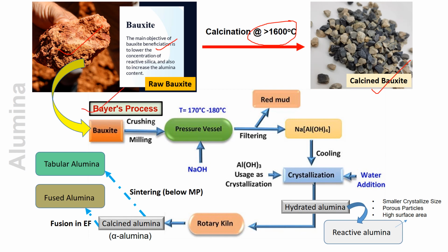Bayer's process converts bauxite to pure hydrated alumina, followed by calcined alumina. In brief, wet grinding of the bauxite ore in rod mills, ball mills or semi-autogenous grinding mills produces fine slurry. Digestion of the slurry by caustic soda is done in vessels under pressure at temperatures ranging from 170 to 180 degrees centigrade. It may vary on both sides depending on the type of bauxite being processed.